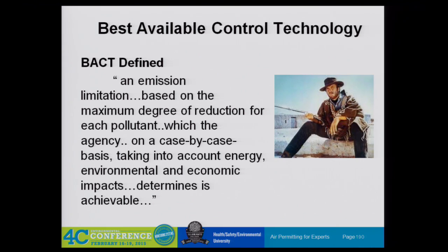All our netting analysis and everything we did yesterday assumes some emission levels, right? How big was the boiler? What controls were on the boiler? How much emissions did it emit? That was all worked into our analysis. Well, if you do a BACT and it changes that assumption of what the controls have to be or what that emission rate has to be from the boiler, it has a trickle-down effect to all the calculations, everything we did yesterday. We might have to go back and redo that whole thing.